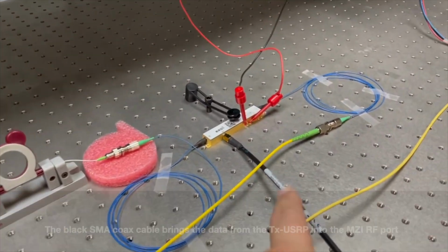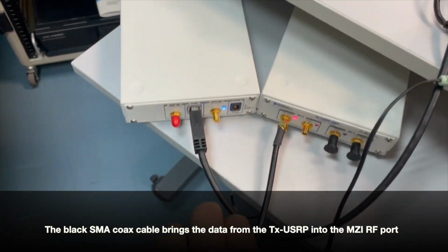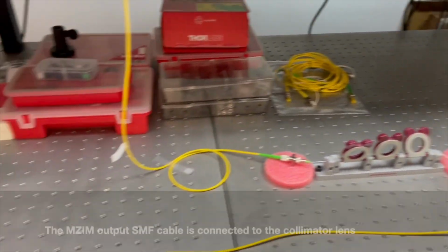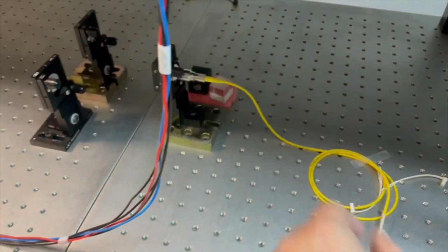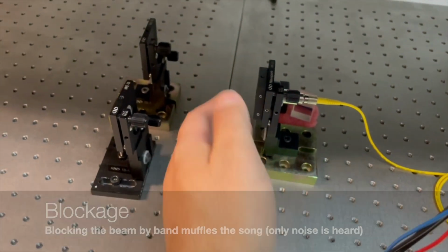The black SMA coax cable brings the data from the TX USRP into the Mach-Zehnder interferometer RF port. The Mach-Zehnder interferometer modulator output SMF cable is connected to the collimator lens. Blocking the beam by hand muffles the song, only noise is heard.